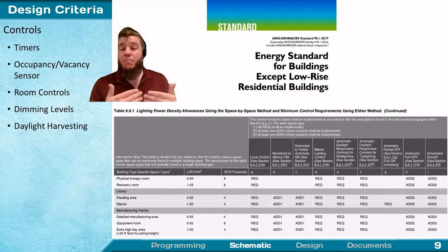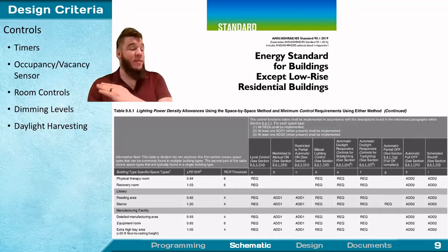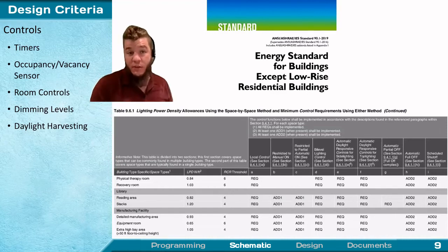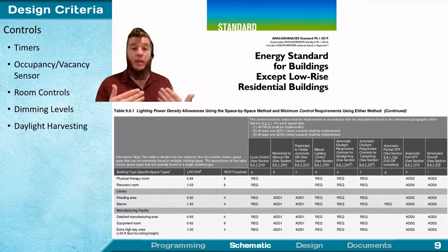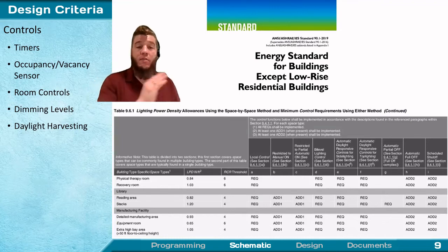And a big part of efficient and effective lighting systems is the controls, because a light source, no matter how efficient, uses zero energy when it's turned off. And so there's a variety of ways you can use to make your lighting equipment intelligent and adaptive to the actual occupants and use of a space. And so here's some options, and these are described in detail in this table.